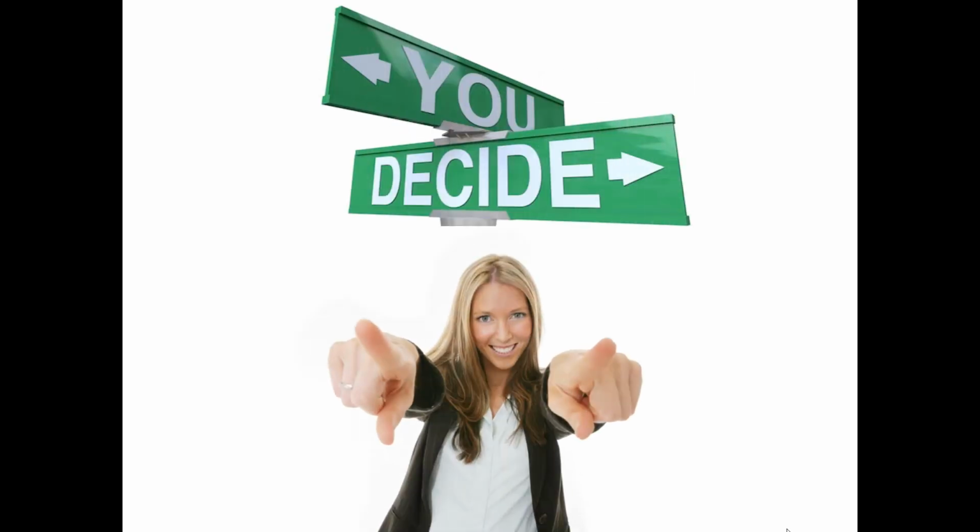So which one should you use? Well, that's up to you. You can do it either way, whichever one is easier for you. The advantage of doing it with the low pass prototype is you only have one unit sample response you have to know, the sinc function. If you're going to start with the appropriate unit sample response for the shape of the filter you want, then you've got 4 different ones you need to keep handy.